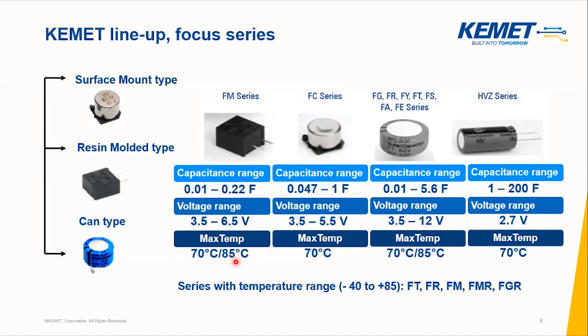So based on that, you also need to look for a specific series according to your specific application, capacitance, voltage, and temperature. The series that we offer with the temperature range from -40 to 85 are these series: FTFR, FM, FMRF, and FGR.